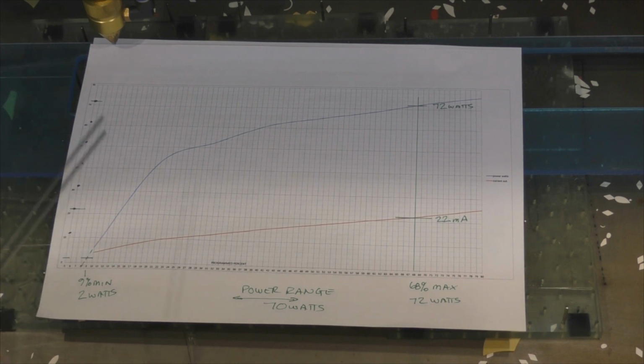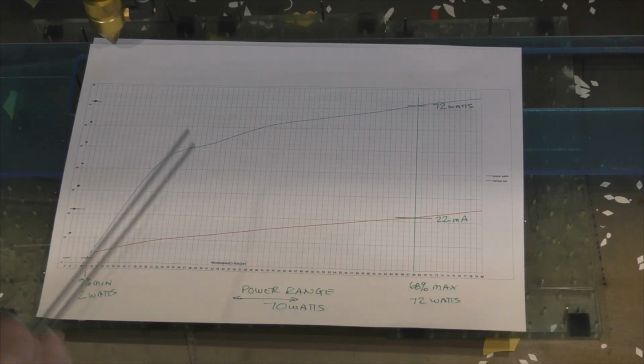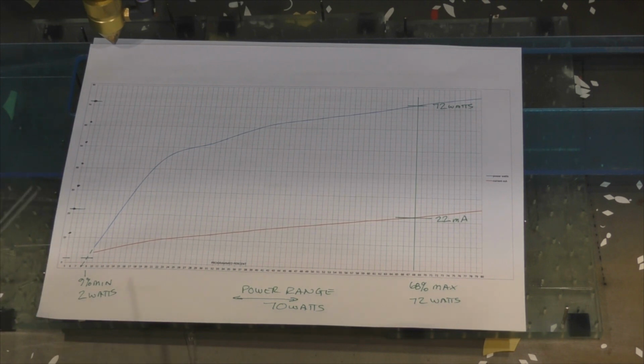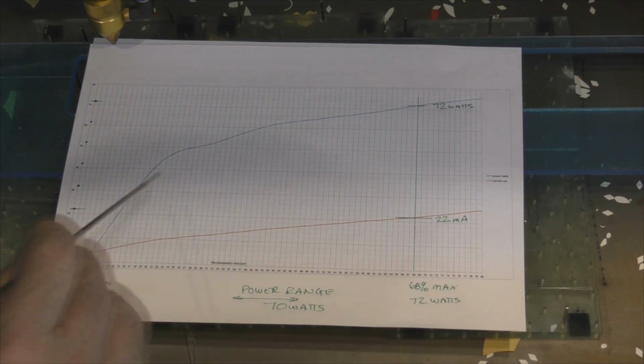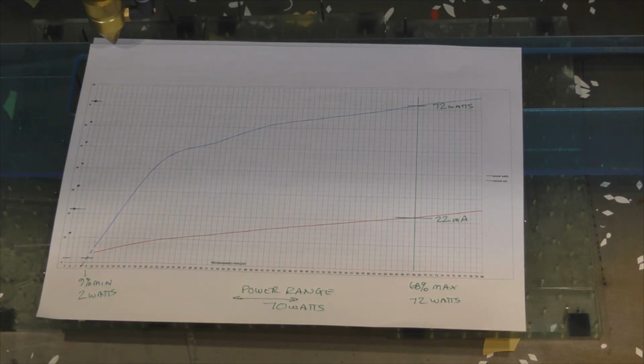But this does give us a problem when we're trying to do 3D engraving, because 3D engraving relies on the grey scale, the shade of grey, to develop an amount of power proportional to the shade of grey. So if we've got a mid-grey, it will select 50% power.